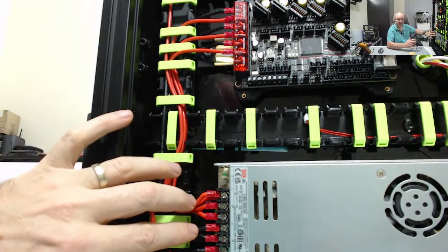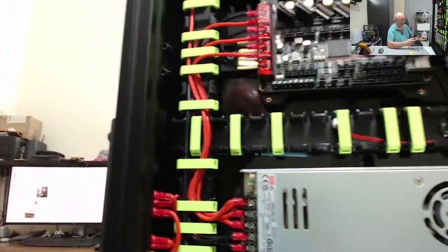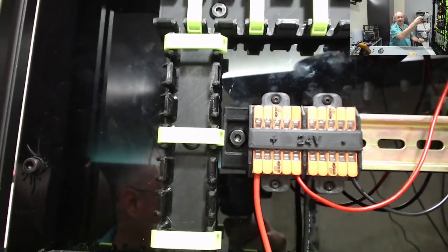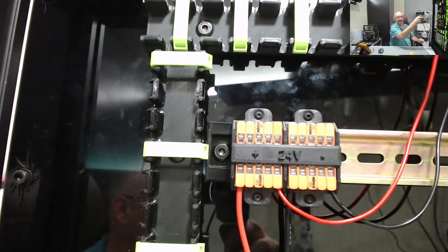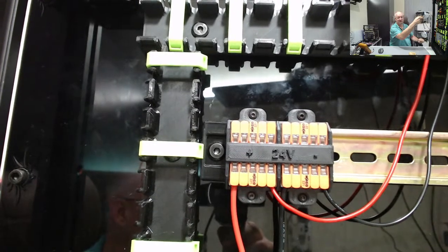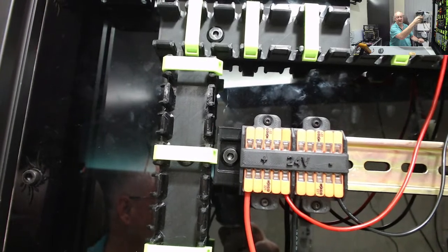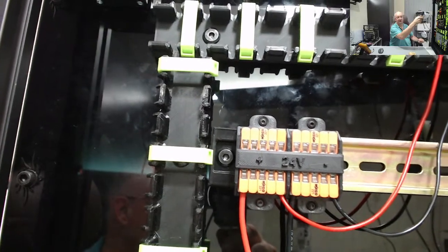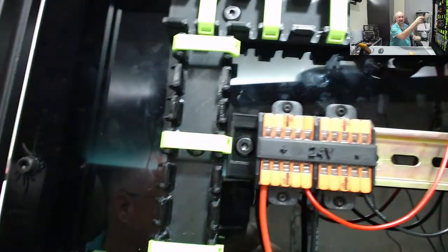And then the last thing you'll probably notice down the bottom here, I've got a double up on 2 wires over here. That's because I took that power and I went all the way up. I have a 24 volt breakout panel there, built up with Wagos, because I'm going to be supplying voltage to different devices. In the future, I will also be putting in maybe multiple print heads, and each print head would need its own 24 volts. So it's already there. All I need to do now is just tap off 24 volts on each one of these.